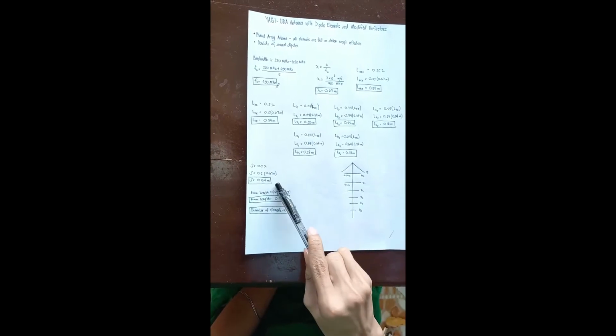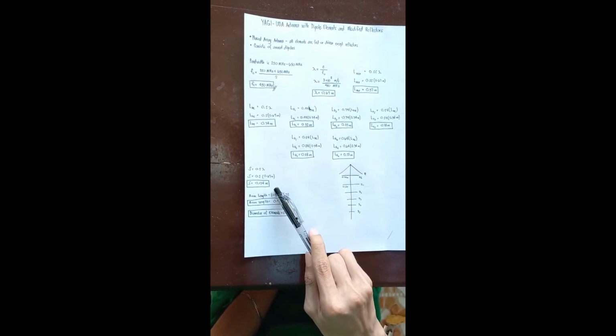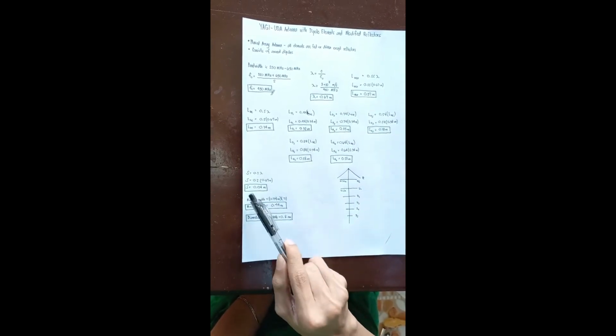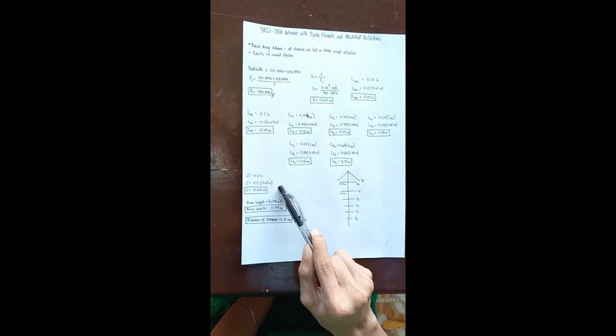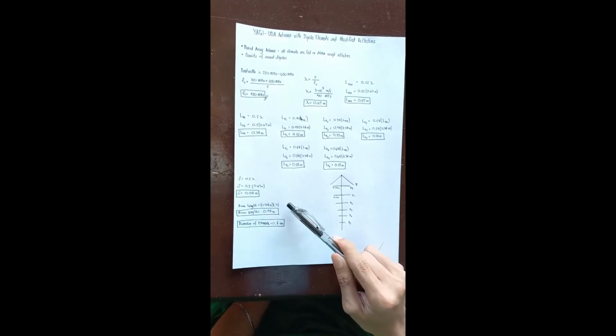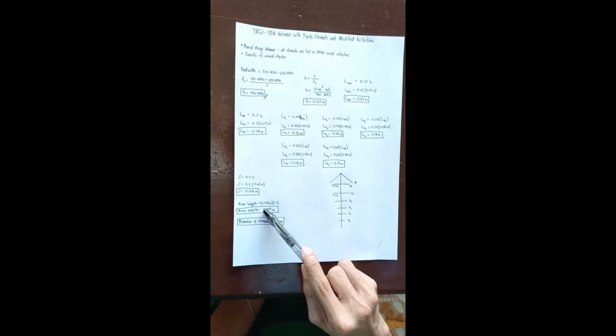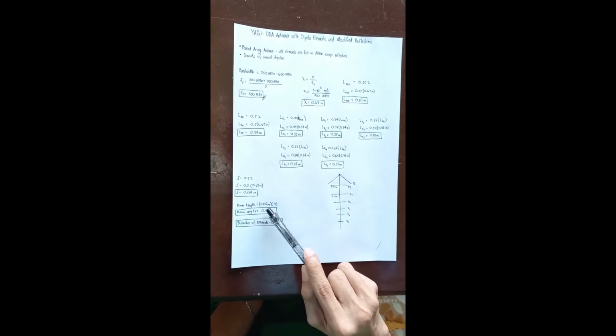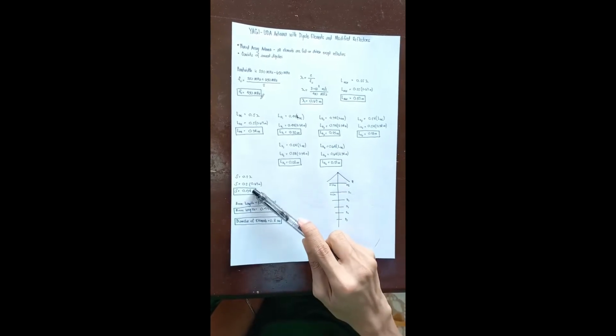For our spacing, it is the wavelength multiplied by 0.2, which is 0.2 times 0.67, or 0.134 meters. The boom length is 0.134 times 7, which is the spacing times the 5 directors plus the driven element plus 1, so 7.